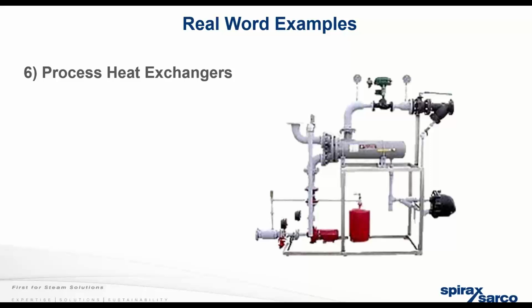I apologize. So here we have our typical process heat exchanger, a shell and tube heat exchanger, process water glycol on the downstream side of the process side. We've got our strainer pointing straight down. It looks great. Sending all that water into a control valve. We've got nice differential pressure gauges on it to measure the differential pressure. Obviously, we're modulating down. Sending that condensate into the heat exchanger and then to a steam trap.